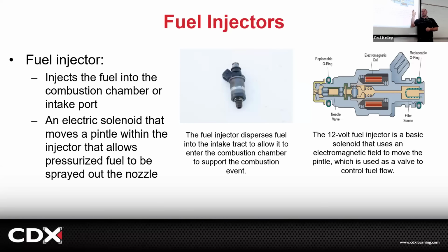Because it went from 50 PSI to 40 PSI, right? I know fuel flowed because the pressure went down. The fuel pump primes it up, holds it. It should hold indefinitely. When I pump the injector, it should drop a certain amount. If I did cylinder 1, it dropped 10 PSI, reprimed it back to 50, commanded cylinder 2, it dropped 10 PSI, reprimed it back to 50, commanded cylinder 3, it dropped 0 PSI, and then 4 dropped 10 PSI. What's that tell me? 3 is specifically, though, bad, but in what way?